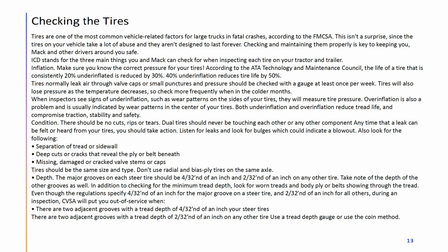Checking and maintaining them properly is key to keeping you, Mac, and other drivers around you safe. ICD stands for the 3 main things you and Mac can check for when inspecting each tire on your tractor and trailer. Inflation. Make sure you know the correct pressure for your tires.